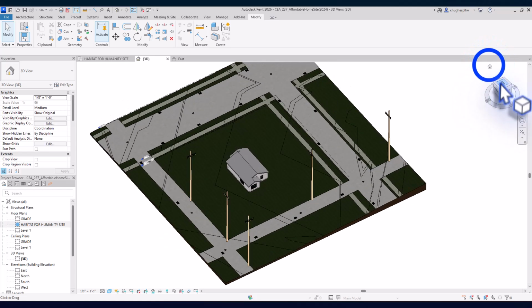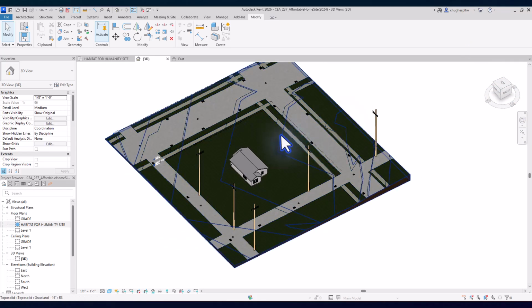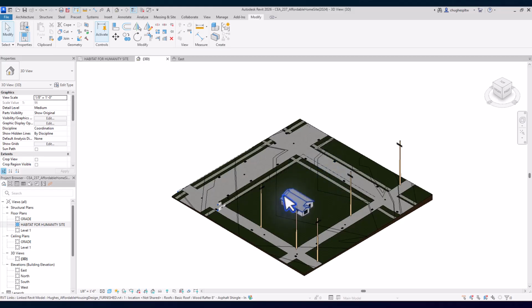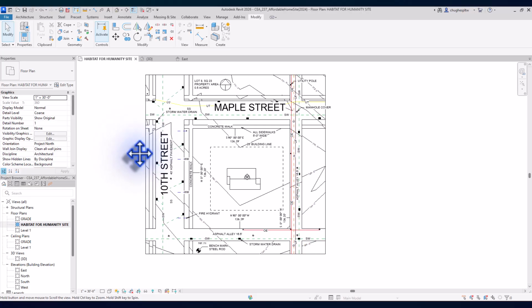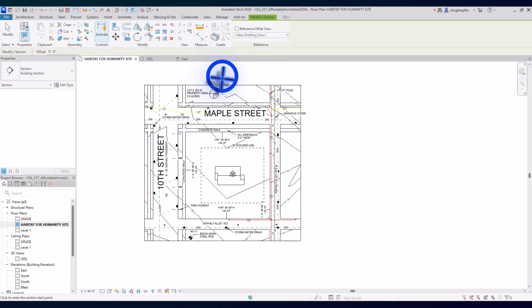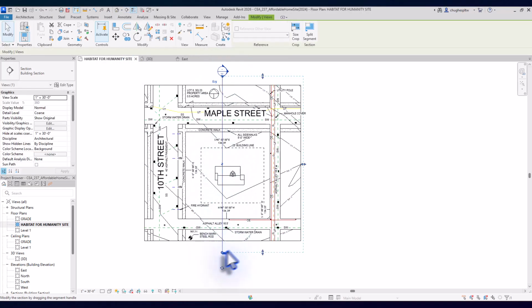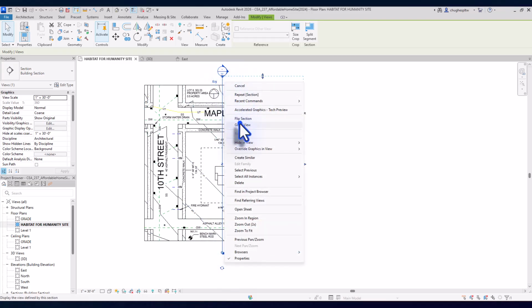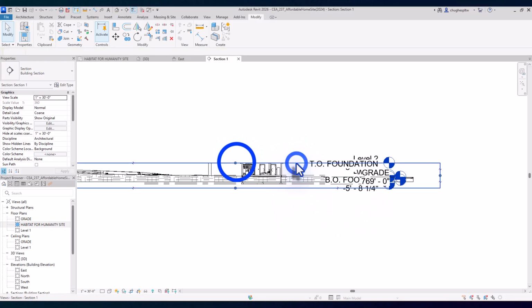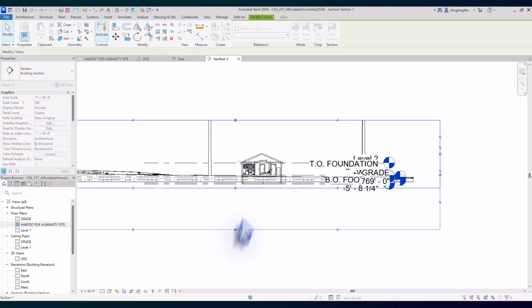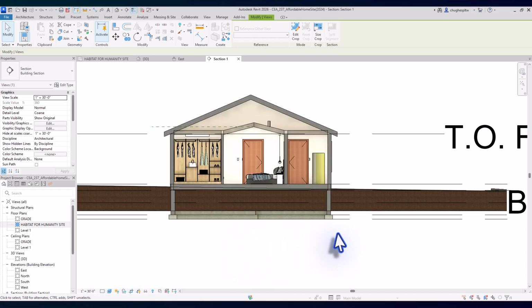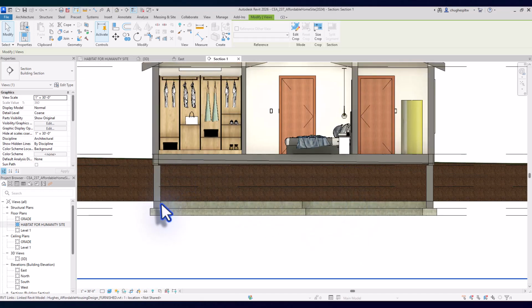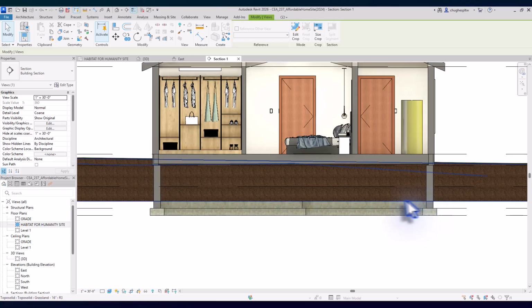What we're going to do now is something called an excavation. If I take a look at my file, I'm going to go back to the Habitat for Humanity site plan and select a section. I'm going to draw a section right through the center, and when I right click, I'll say Go to View. Once I open the crop region a little more and change this to realistic, you're going to see that our Toposolid runs right into our foundation. The ground just runs right through that.